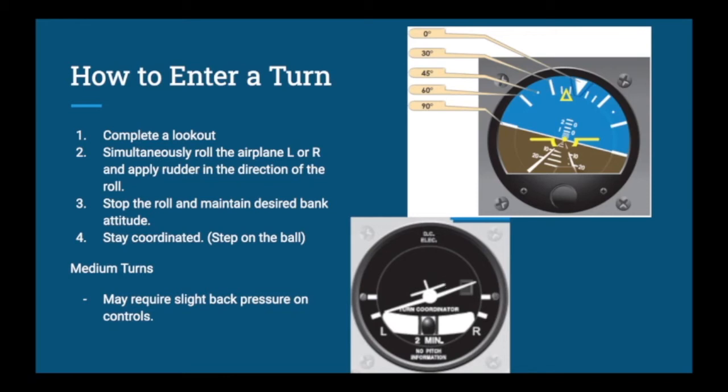Now, I mentioned we need more lift in a bank in order to maintain level flight. So very slight back pressure on the control may be required just to keep the nose up, maintain level flight. The more you bank, the more noticeable this effect is.